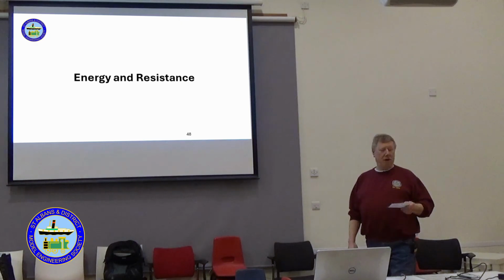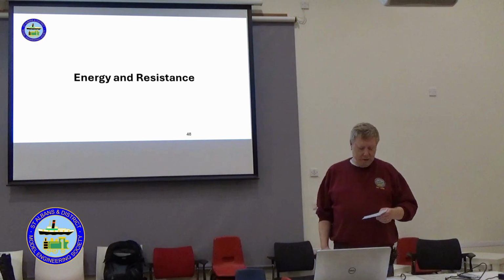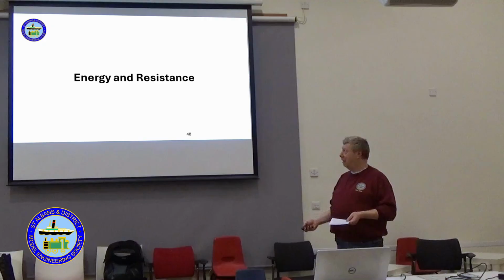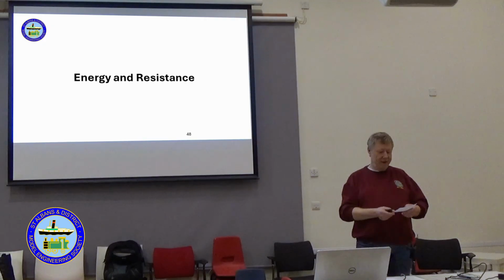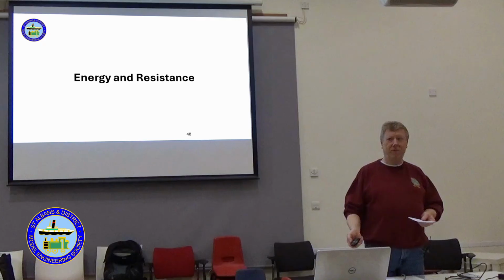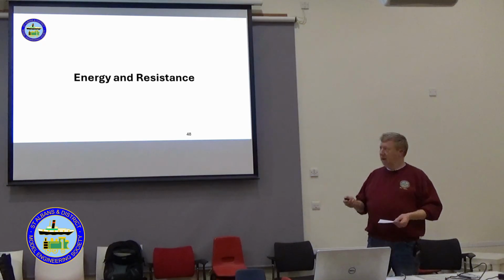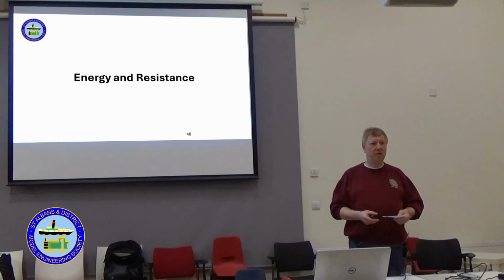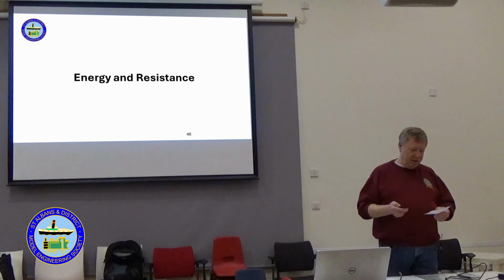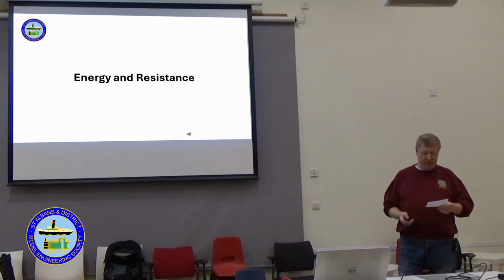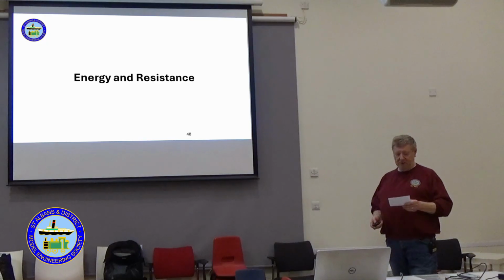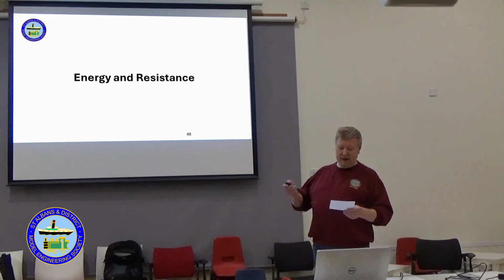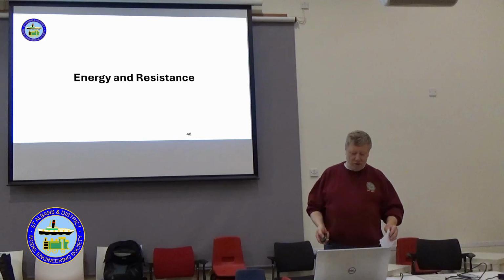Obviously, when you've got a railway travelling over very, very long distances, running that railway is basically about managing energy. Energy is fuel, and fuel costs money. So one of the important things is all about resistance to motion. That resistance varies with speed, so that affects how fast the train can go. It affects the size of the locomotives you need, where those locomotives need to be put, how much fuel you take, and even what route you take.